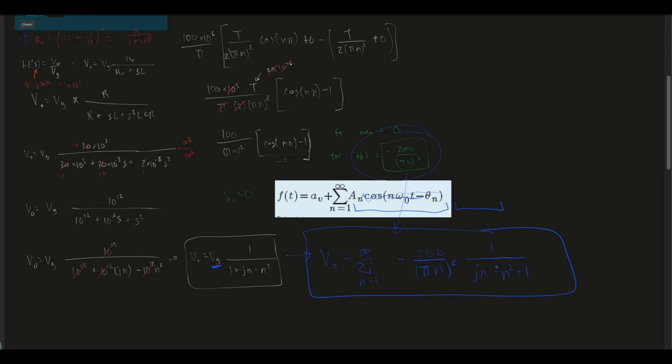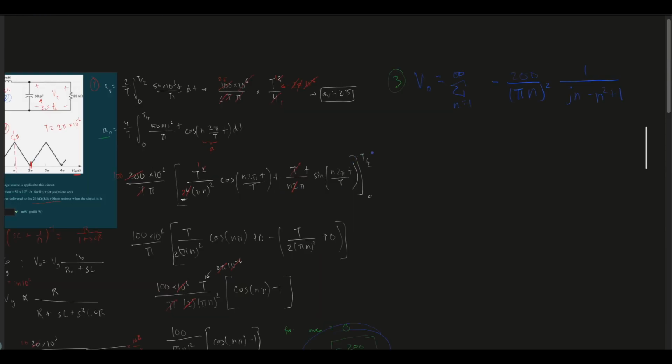So now we need to find our Vrms. That is going to be step 3. Before we go any further, to find power, we're going to say that power is equal to our V times our I. We don't have I here. We're basing this off the 20 kilo ohm resistor. Remember, it's asked for that in the problem. So instead of I, we're going to use Ohm's law and say voltage over resistance. And so we can rewrite this as our Vrms squared over our resistance. We know our resistance is 20 kilo ohms, so 20k, that's 10 cubed.